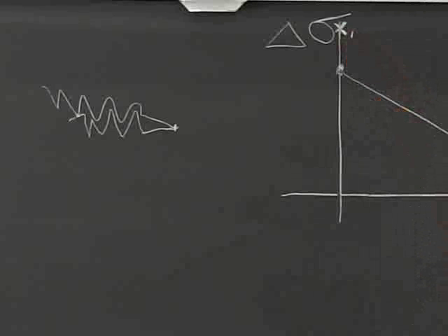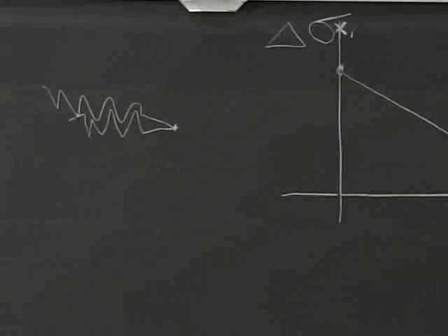So this is very rough here, but the idea is you get into the safe zone. And you try to have a margin there, given how the things get torqued up and the friction and everything that comes into making a preloaded connection. But that's the reason for, I'll say, caring about it. It's not so much to make sure that bolts don't come loose. It's to reduce the amplitude.